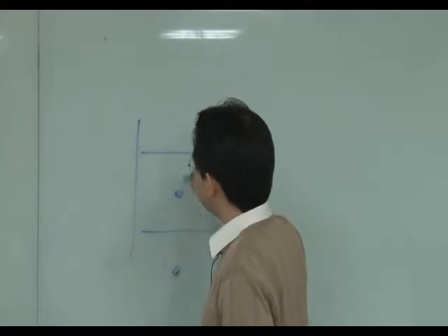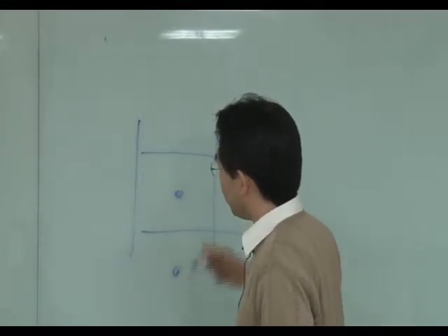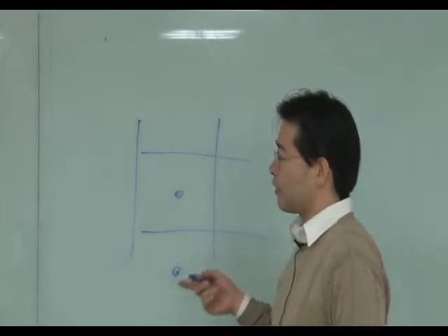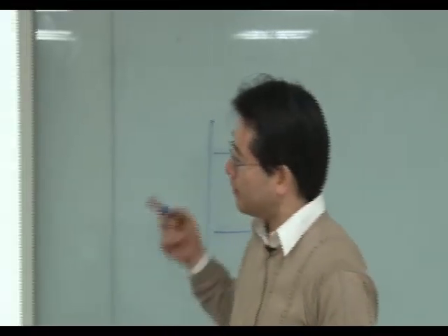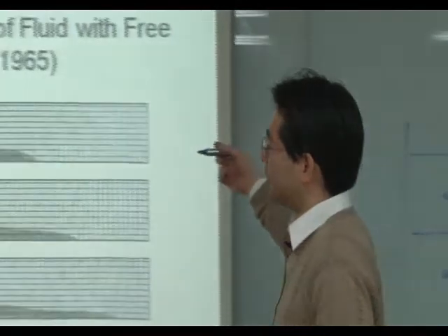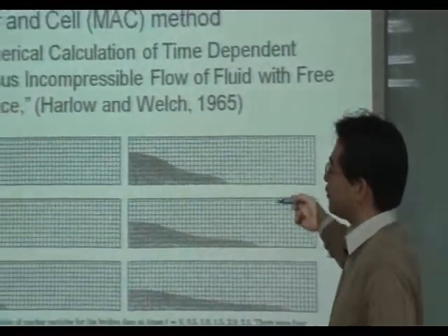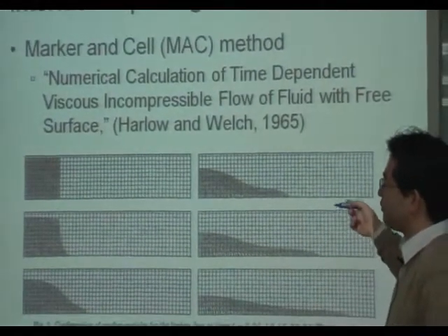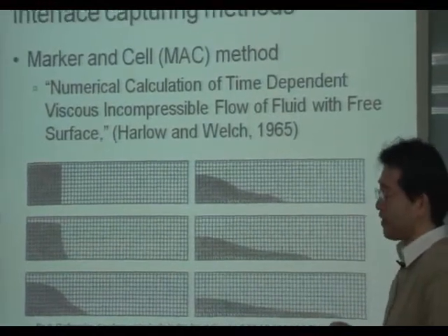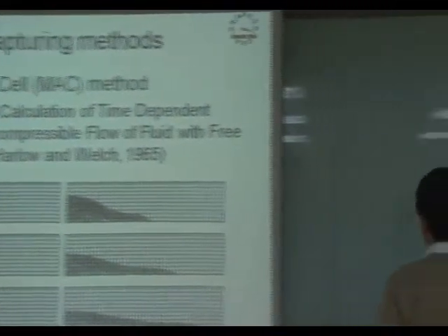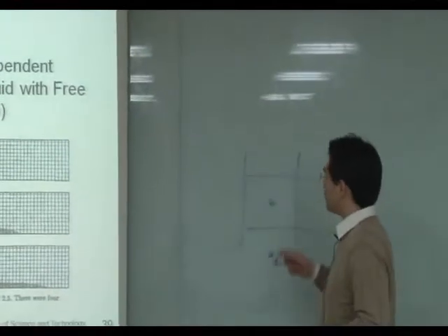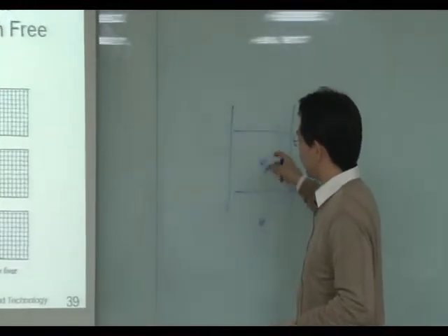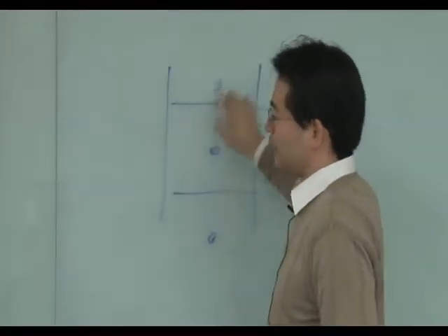In the initial condition, they define control volumes. In this age, the finite volume method is not known, so their definition is the finite difference method. But they are using a staggered mesh, and the pressure point is also in the computational domain.